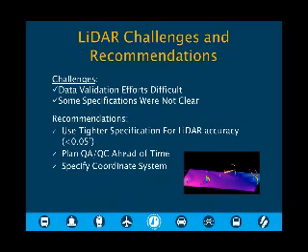We had some shots and we were able to check it and make sure that it was within specs, but it was a little close. Some of the specifications we had put out there weren't real clear, like the number of survey shots and that kind of thing. We didn't quite spec it tight enough, I guess you might say. And one of the challenges was using a tighter spec for the LiDAR accuracy. We had it at 1/10 of a foot.